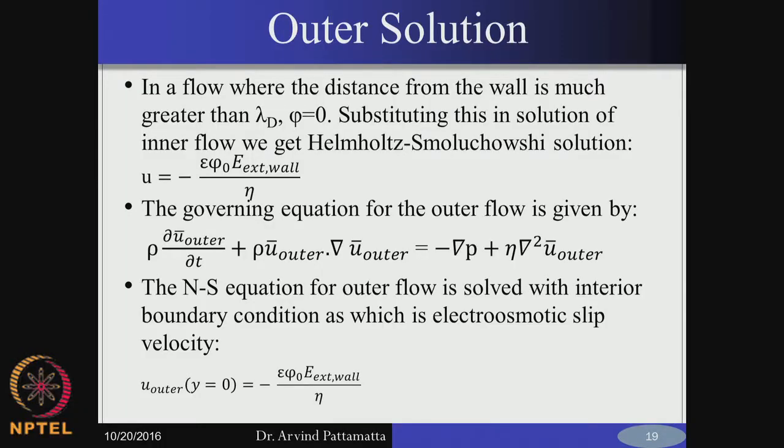For the limiting case where delta p equals 0, you have a fully developed, steady state profile. Then what will be the value of bulk velocity? Same as that of the boundary condition. All these terms go to 0, so you have d square u by dy square equal to 0.